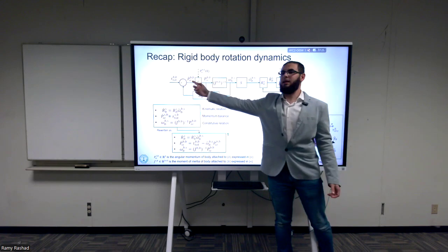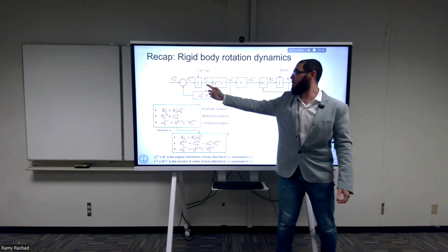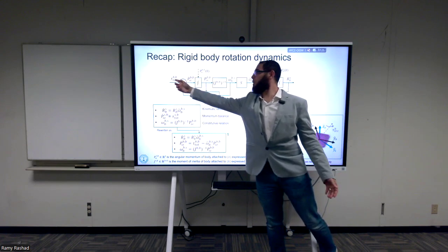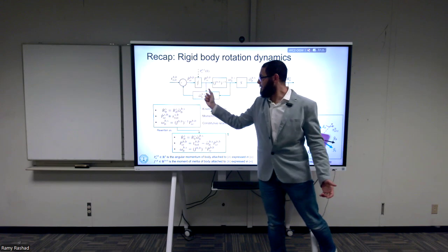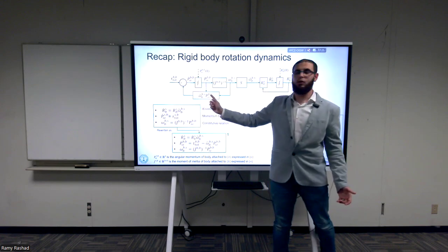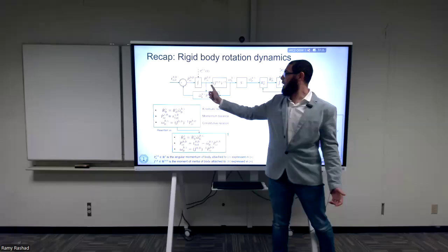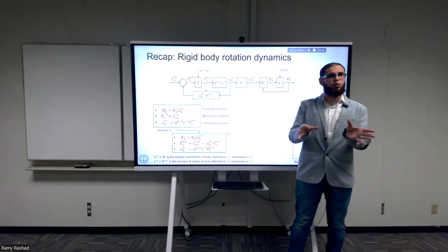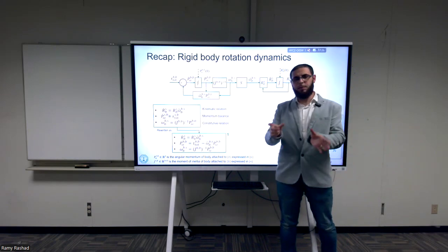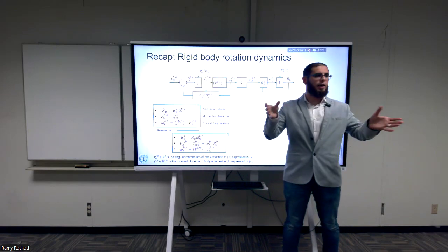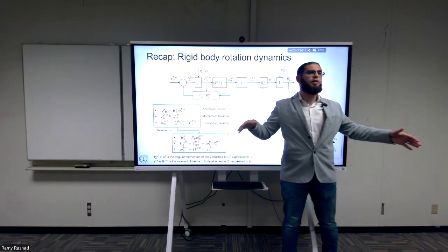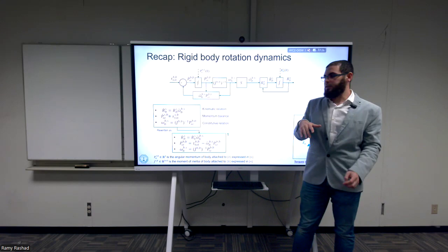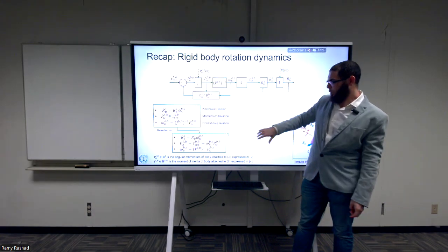And the angular momentum, I can integrate it from the rate of change of the angular momentum, and I have the difference between the total applied torques and this cross-coupling term between the angular velocity and the momentum. Okay? And this was the term that we derived last time. And there are many different ways we can write this term. And usually people, depending on how you write it, the equations get different names because they were derived in different ways. We're going to look at it, not today, but maybe at a later stage. I'll tell you these names, what they are called.